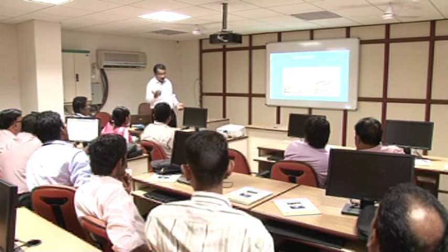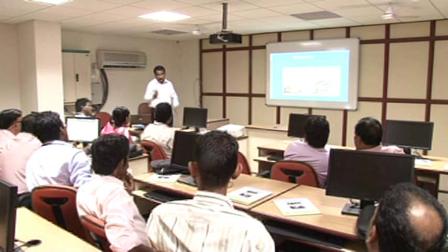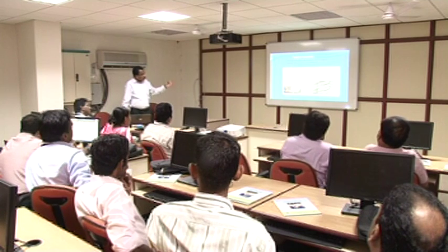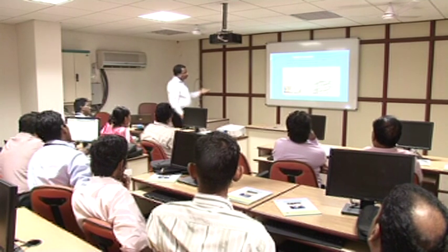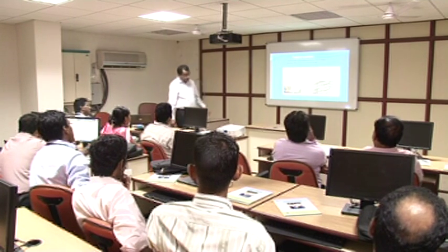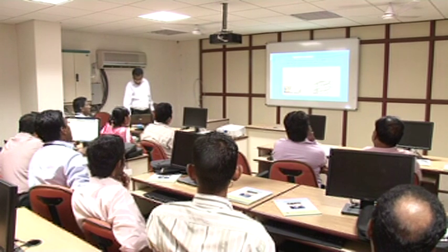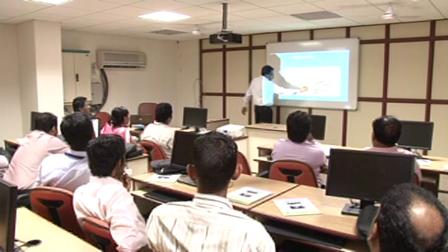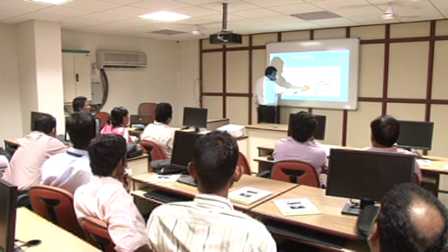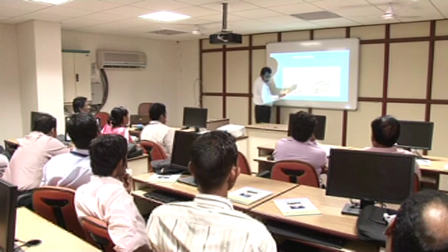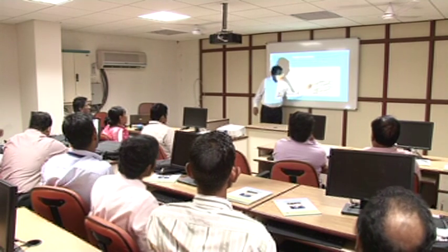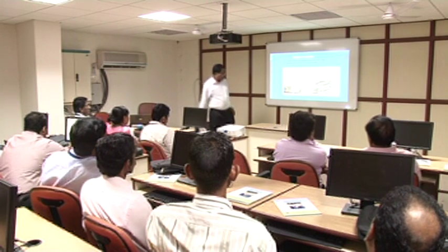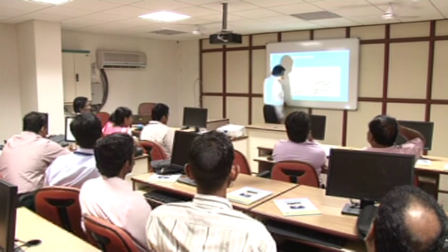Suppose if we are going for data, we should know the spectral range. So for that purpose, this resolution is made. So this is representing the number of bands in which the image is taken. That is the meaning of that one. So we can see one band, that is blue band. This is corresponding to blue wavelength region or the visible region. So that is sensed by one. We can keep one image, one datum. So that is blue band.